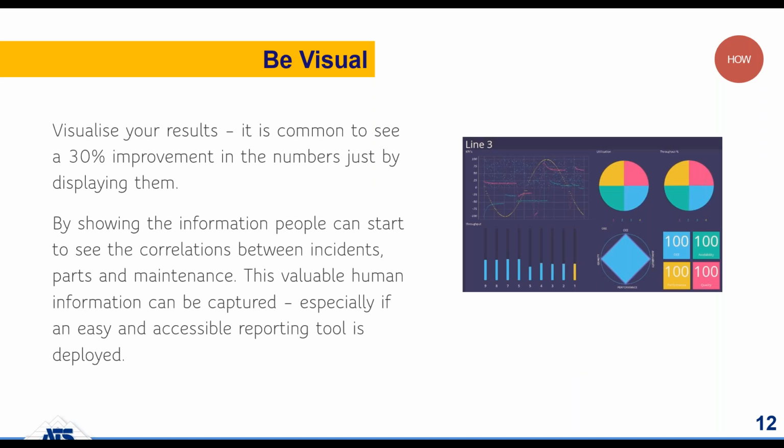Collecting data that you cannot see will not bring any value. Visualization: it is said it's common to see a 30% improvement in OEE numbers just by displaying them. By showing the information, people can start to see the correlation between the incident parts and the maintenance. This valuable human information can be captured, especially if an easy and accessible reporting tool is deployed, right? By creating virtual dashboards and reports, you will be able to visualize how the facility is performing and also respond to any breakdowns or shop floor issues, right?